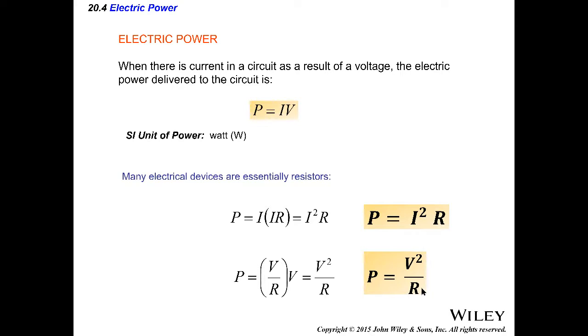Now, even though this microwave oven is rated at 1500 watts, when you plug it to your household circuit, if your voltage is not 220 the way it was designed and manufactured in Asia or in Europe, then when you use it, you find that it is not at the 1500, it's like 400 watts. That means that I'm not cooking what I thought I was cooking.